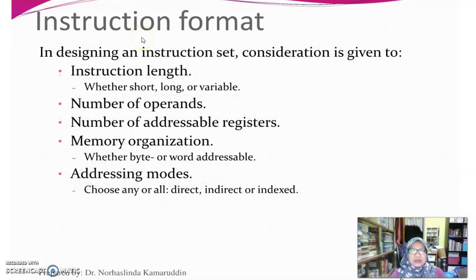Of course, when you want to design an instruction set, you must consider these few characteristics. First, the instruction length, whether you want it to be short, long, or variable. Number of operands, which basically depends on the number of registers that you have. Then the number of addressable registers. What it means is that the data can be overwritten.